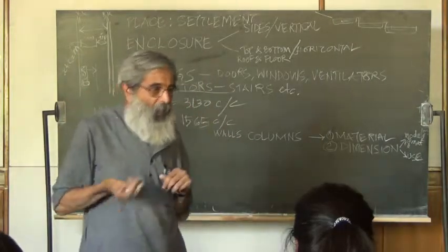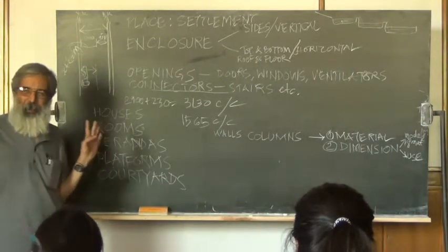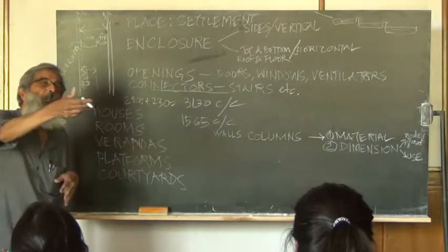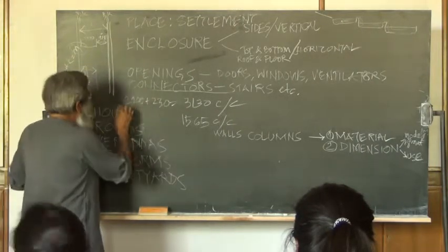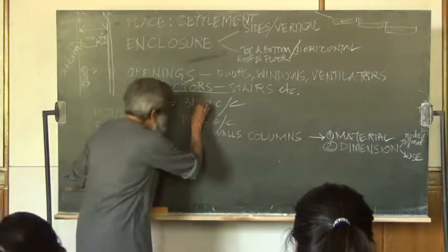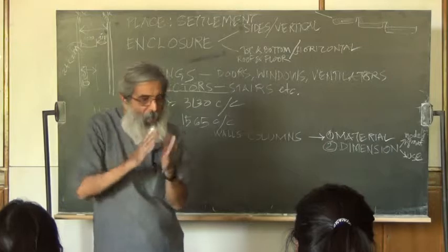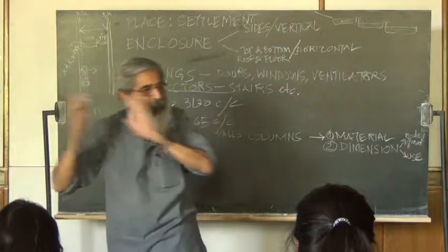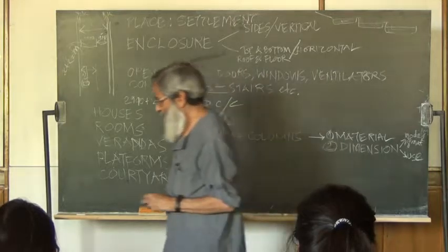Just check that. You can see now, this dimension, instead of being this, can I make it in brick dimensions? So 2300, then another 3 weeks, 2990 is a brick. I use brick. I adjust it a little. Then I get this one different, etc., etc., etc. And I will get all dimensions in the multiples of the material that I am using and the multiples of each other. That is my attempt, to get that.